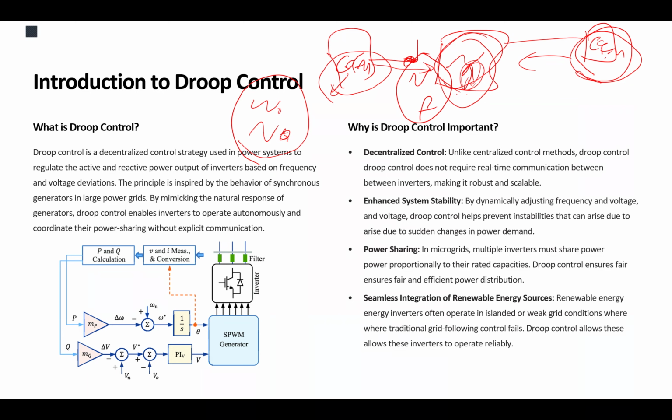Yeah, they both want to fix the frequency at, for example, 60 hertz. If anything happened in the grid that jeopardized that, they would force the frequency to go up or down to that 60 hertz. That means they either have to inject more active power, or lower their injection of active power, to regulate the frequency at the point that they want.